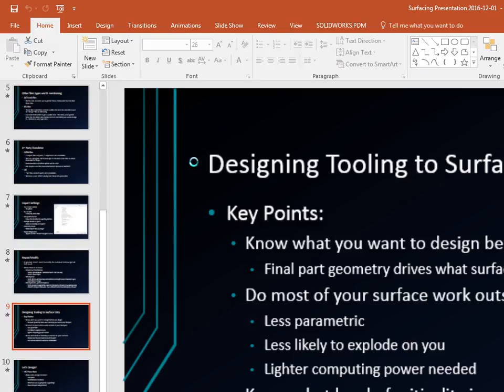That's a case where I think face fillet might work, if I take this face. Whoa, that's kind of weird, because it didn't even go to this face. But I've had it before where if I tell it it's okay to go into this face, by using face fillet, that will help it to solve. At least you can cut it with CNC. Right, exactly.